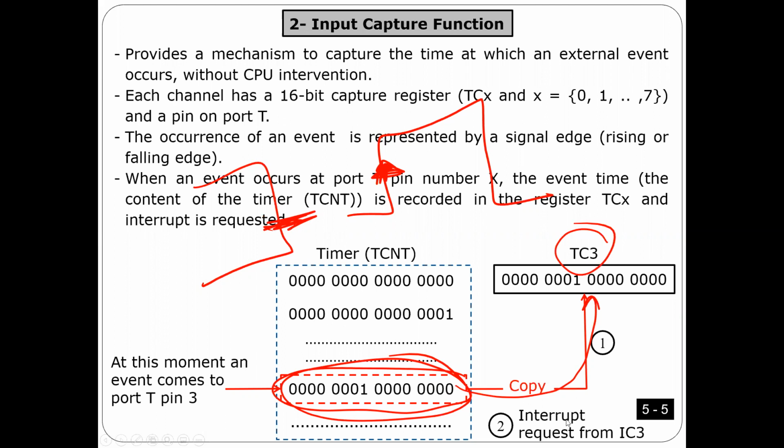And then it triggers an interrupt. In the interrupt subroutine, you have to take this value from here and store it somewhere, because I need one value here and one value here. Once I have both, I do the calculations. Very easy, you don't need to do anything. When you go to the subroutine, the count is already stored in this register.